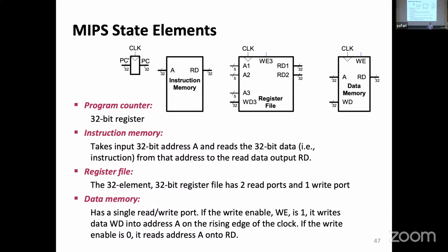It's actually a bit of a tricky thing. If something stays in your mind, saying, why do I have data memory and instruction memory separate? It just makes this part of the explanation much simpler. In most practical cases, the instructions and the data will be in the same memory space, but at very different places of the memory. So seeing them as two completely independent memories makes my life explaining here much easier, and this is why it's used like that. It wouldn't be so difficult to show that they could be one and the same memory.